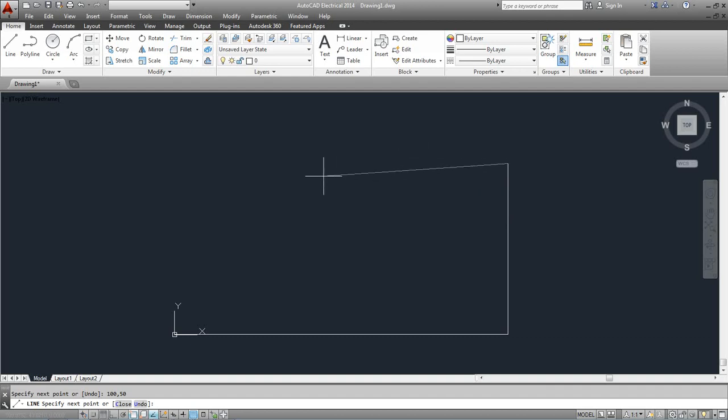So this vertical line represents our width of rectangle. So now we need to go in left direction. For obtaining this point, how much are we traveling? We are only traveling in y direction from the origin point. So our coordinates will be 0, because we are not traveling in x direction, comma 50, and press enter.